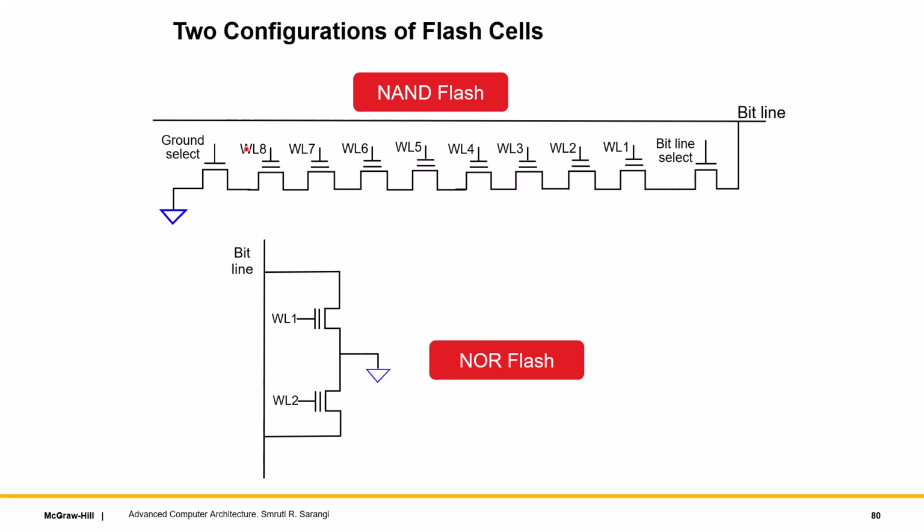So this is a basic flash cell which is not very hard. We are setting two threshold voltages pretty much by programming or by erasing. And to read it, all that we have to do is set the gate to source voltage to something between Vt and Vt plus. So there are two configurations.